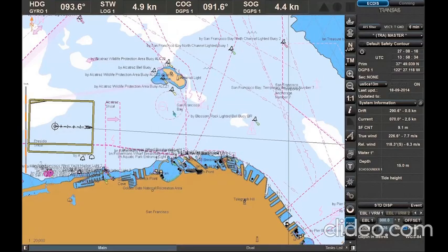System Archive. The archived system parameters are saved on the computer hard disk and can be available for viewing through Ecdis Task, Playback, or Data Tool utilities, which were mentioned earlier in this module. The data is saved locally on each workstation and is not synchronized.